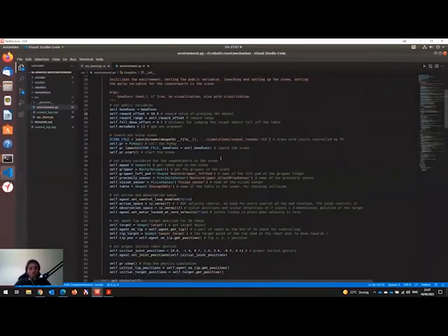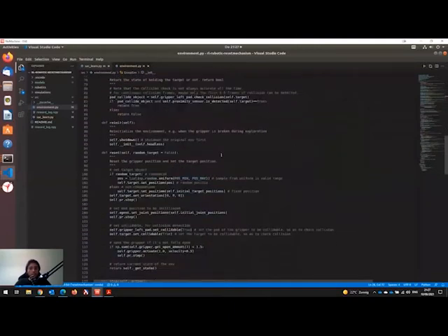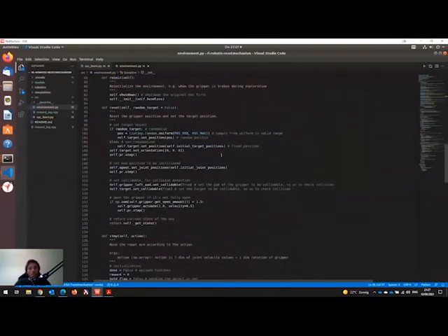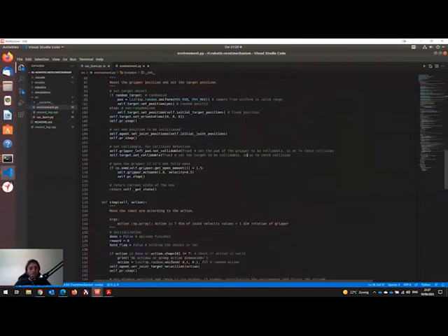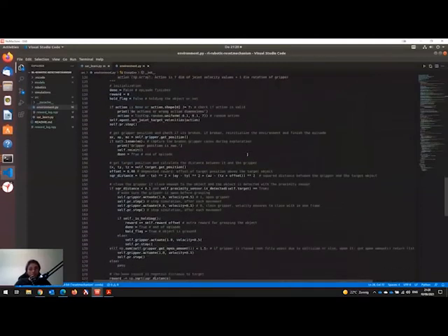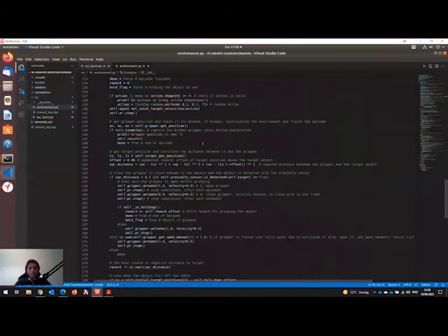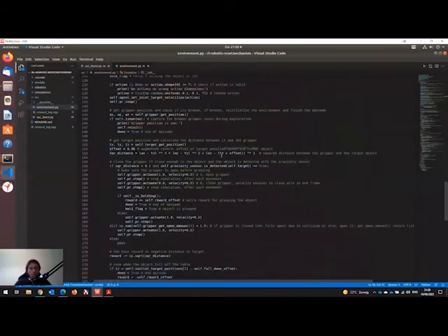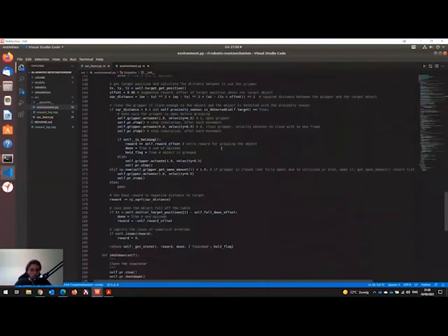As a solution, a distance penalty was added from the gripper to the cube, as well as a penalty for the collision between the gripper and the table to avoid damage to the gripper, which constitutes a dense reward.